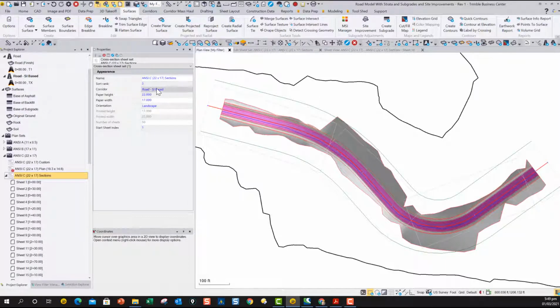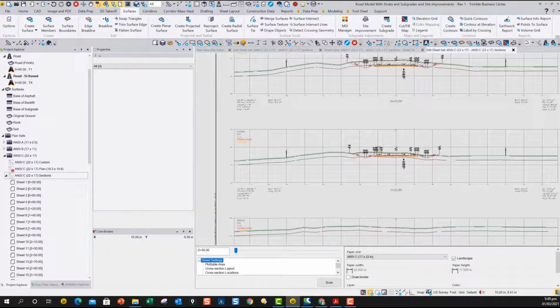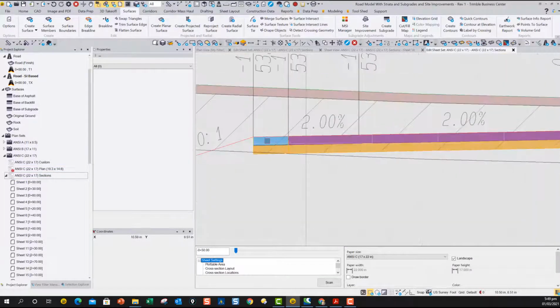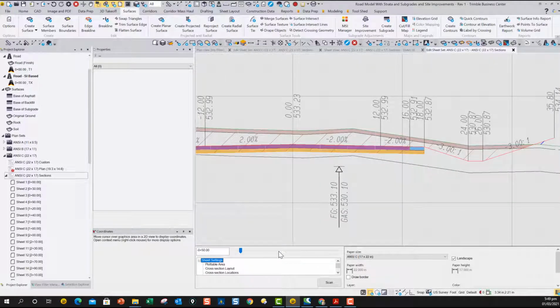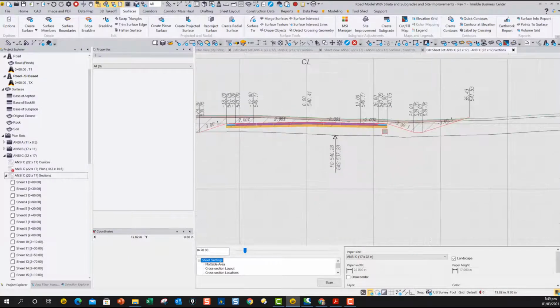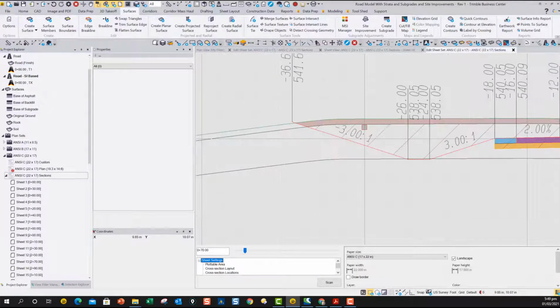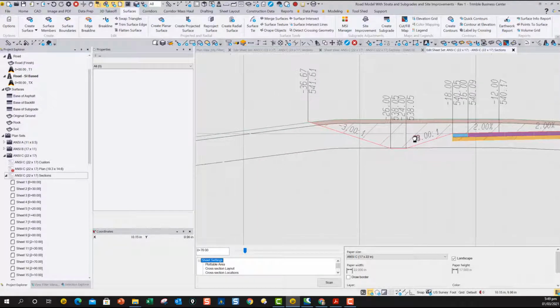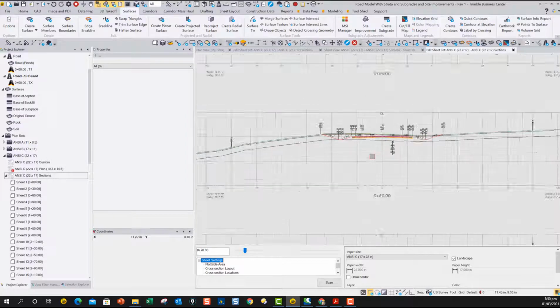I reference the site improvement based road, and then I basically go to the editor to make sure it looks okay. And in the editor you can see that it's picking up this backfill material, the subgrade, and the pavement all the way through here correctly. And if I jump backwards and forwards through here, you can see that the cross sections, no matter where I stop, are looking good. And I'm getting all my materials. Now I'm not using solid fills like in your case, but this is solid fill, so this would be the same if you chose those. You can make them transparencies. This is solid fills down here, so all this can be made in solid color if you want it to.